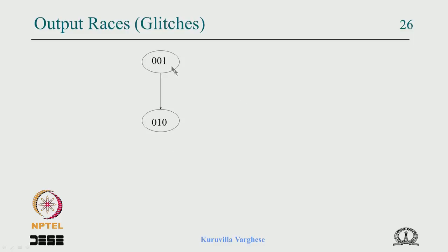We do not know whether it occupies 8 states, but more than 4 states, which forces us to use 3 flip flops to implement it. Assume there is a transition from 001 to 010. When the clock comes, with no input condition, this transits to this. So Q0 is going from 1 to 0 and Q1 is going from 0 to 1.